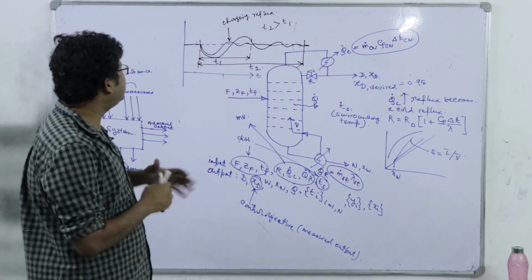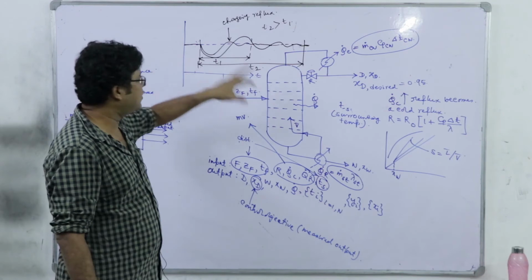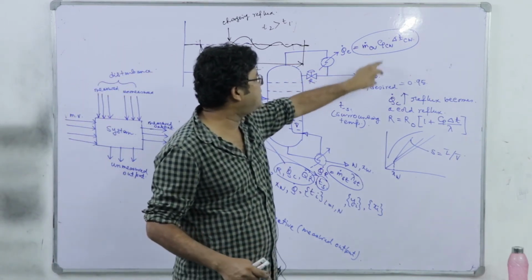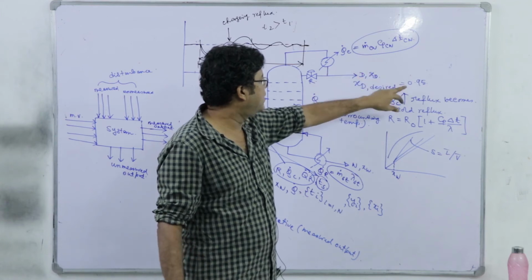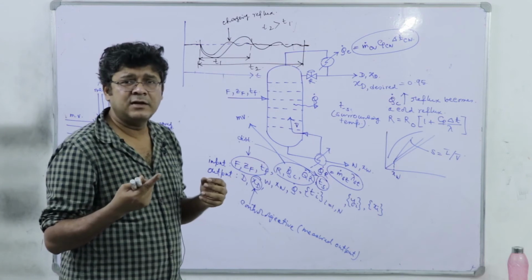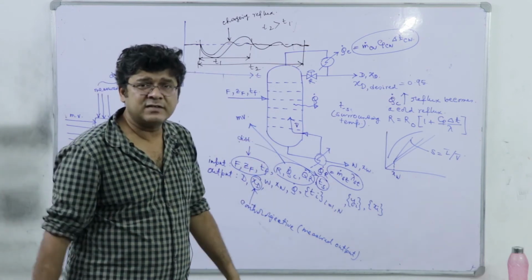So over that interval, whatever it is, T1 or T2, we are getting distillate that's not matching strictly with the desired condition. So we have to either recycle it back to the feed tank right here, or we have to simply discard it.